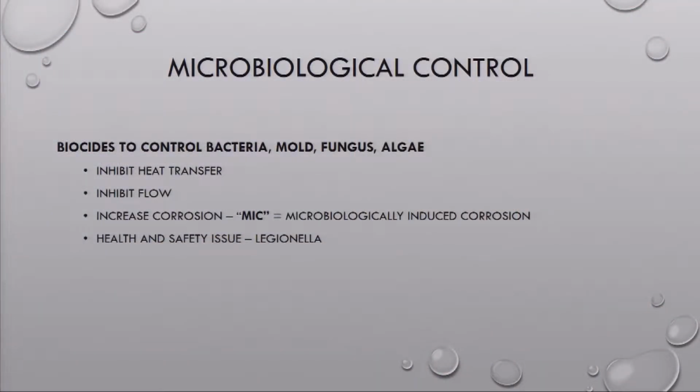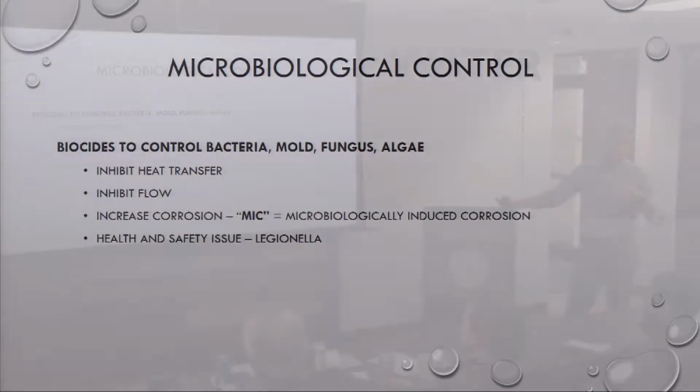So microbiological control. Bacteria, mold, fungus, and algae. Those can inhibit heat transfer. So just like scale, it can line your tubes.